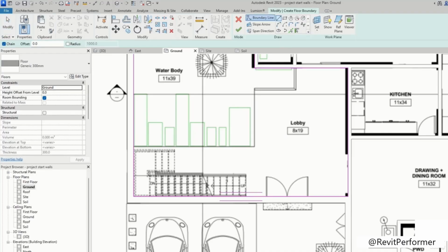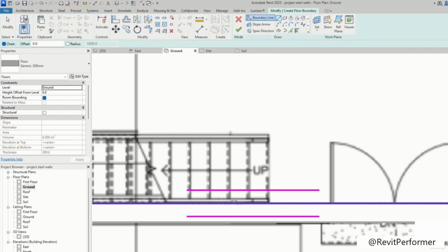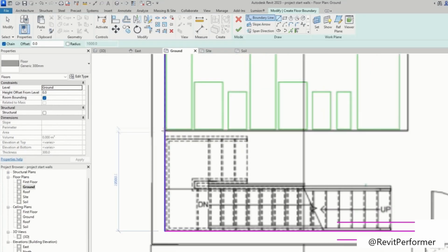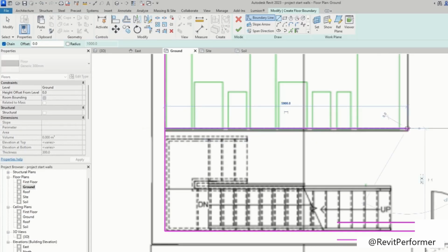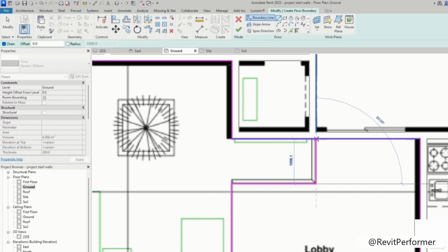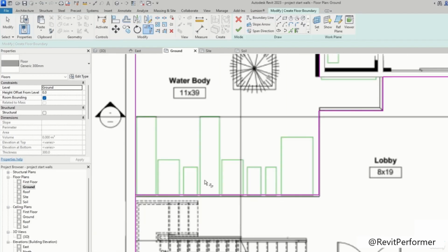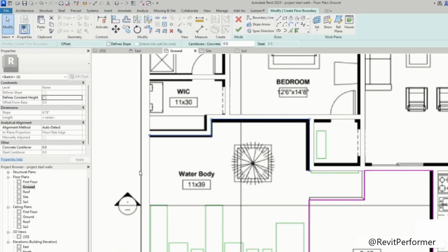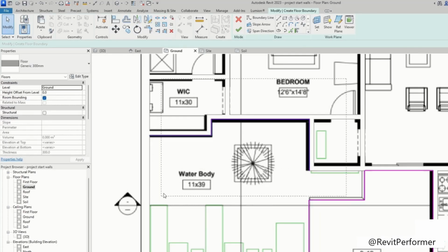Okay, for that, we will use the manual line tool. I will go from right over here, like this, or no, it goes like this. Draw according to the other floors. Great, that's it. Go over the TR again and trim and extend depending on your dimensions. Trim and extend. Select all the extra lines that we have, like this.